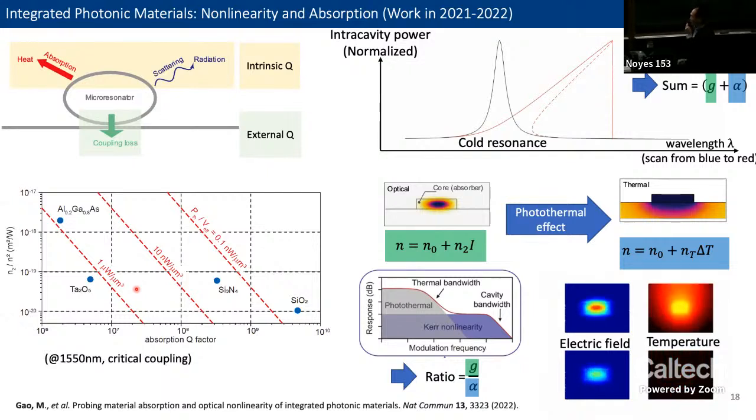At those wavelengths, we can show there is a strong absorption peak of silica, which helps you understand what is contributing to this absorption loss, by looking at the absorption loss at 1380, which is close to OH absorption.